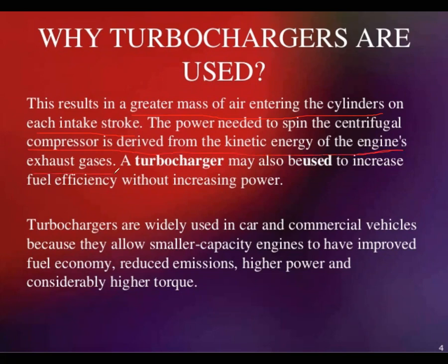So exhaust gases are used to run the compressor via the turbine: by sending exhaust gases to the turbine blades, the compressor runs. The turbocharger may also be used to increase fuel efficiency without increasing power.